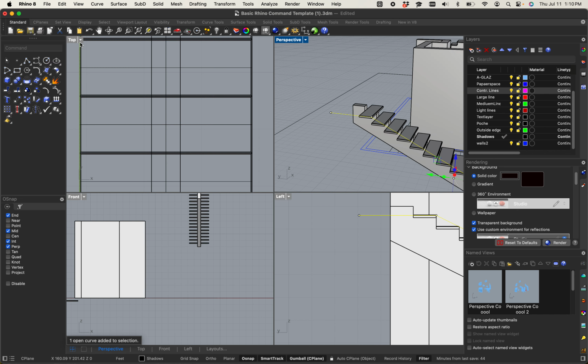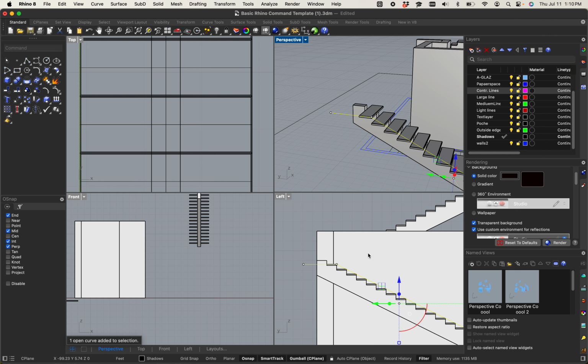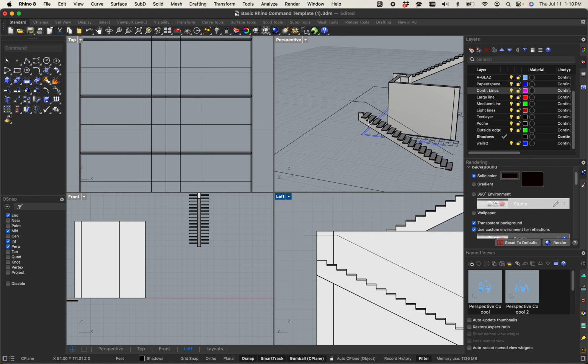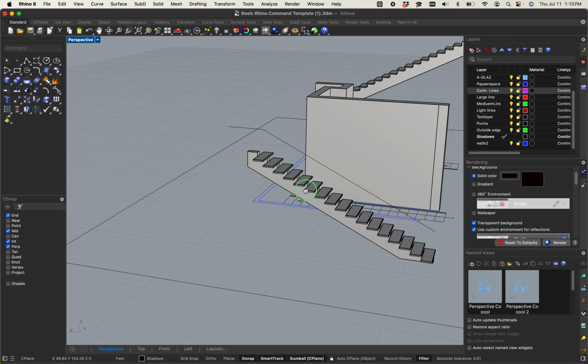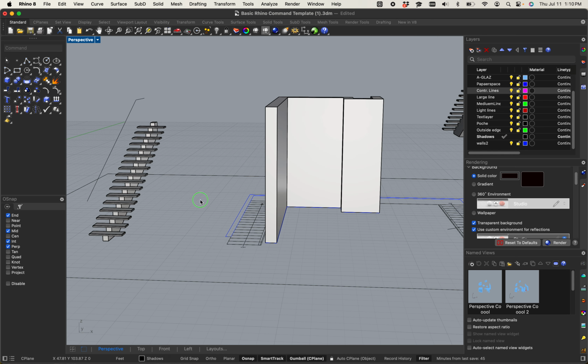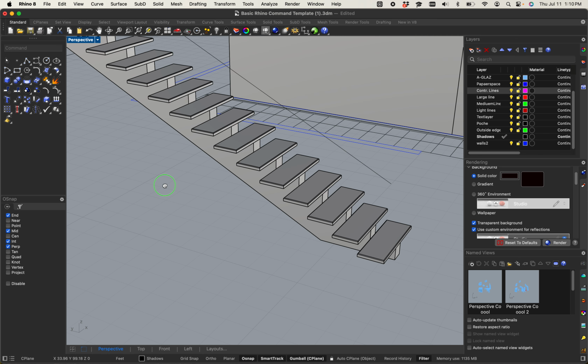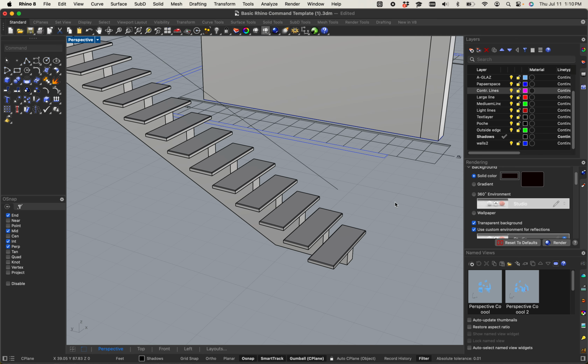I know that handrails are 36 inches from the stair, so I just need to move it, say 36 inches, up in the Y direction, sweet. And as you can see, it's more like a wireframe right now, right? Oh, maybe if I wanted to add to that, I could still, right? So I could draw a line, take that in, draw it out a little bit, and then of course connect those. Type in join. Sweet, it's joined.